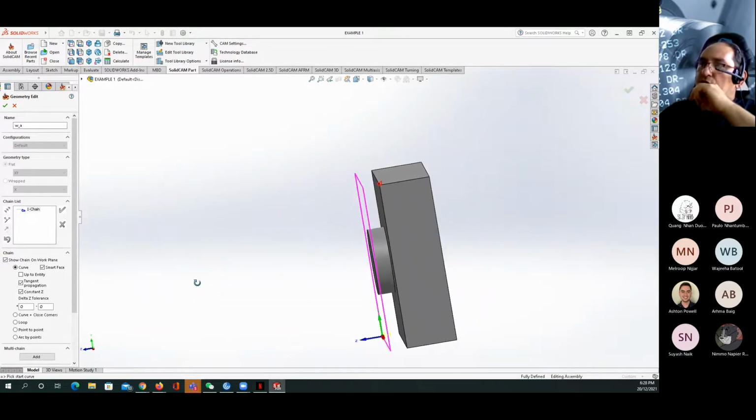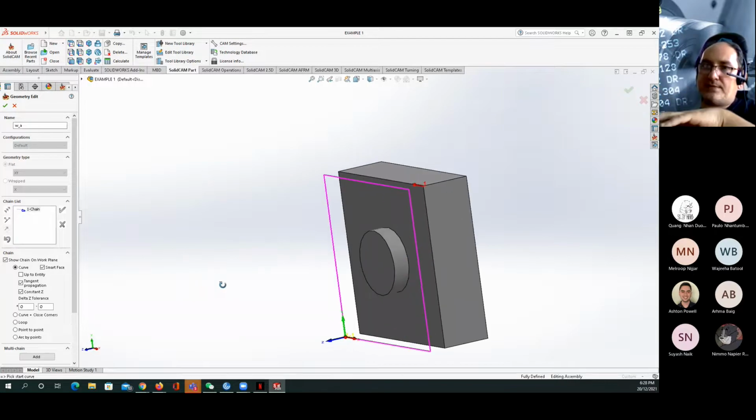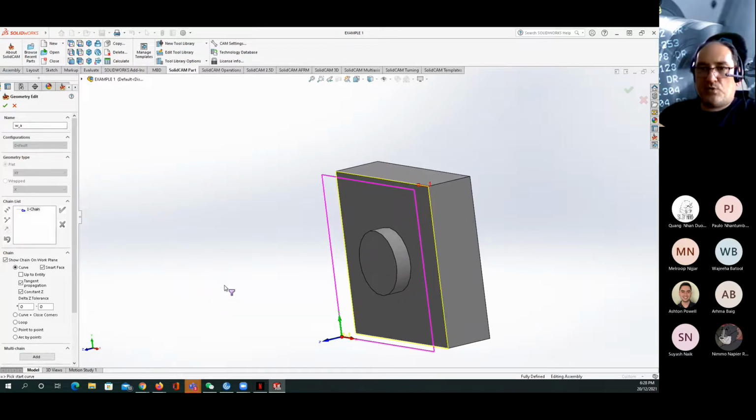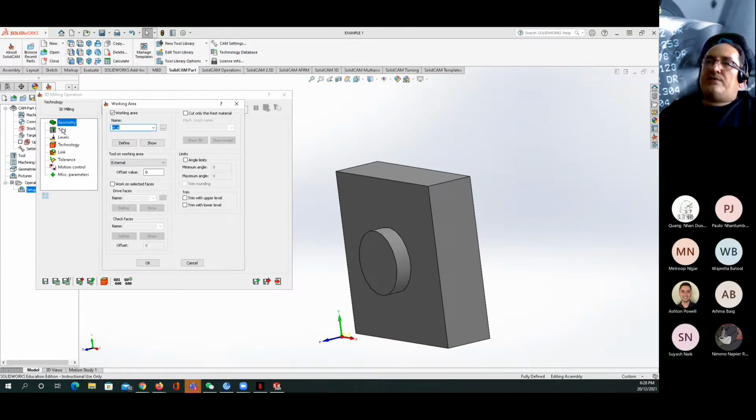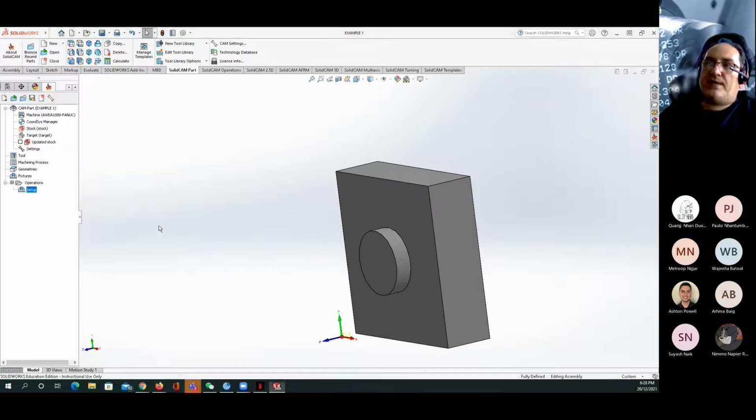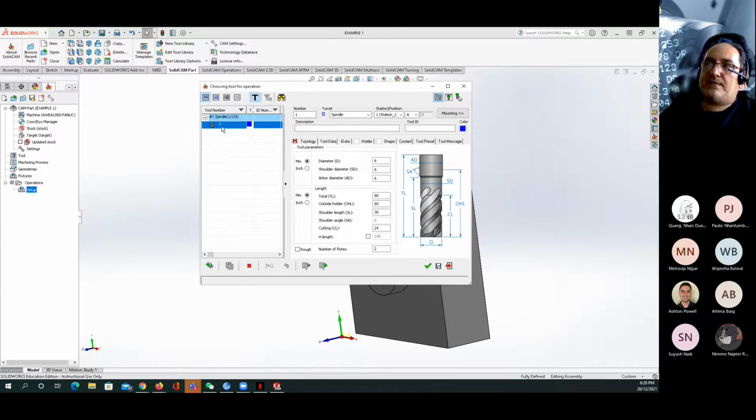Now, why I need to do that? Because I would like to cut 2 millimeter, which been extra added to the work part, to reach the level of the 0 for the top surface. So I click yes. The tool again to use for this operation, need to be defined. So the only tool I have is the 6 millimeter diameter.